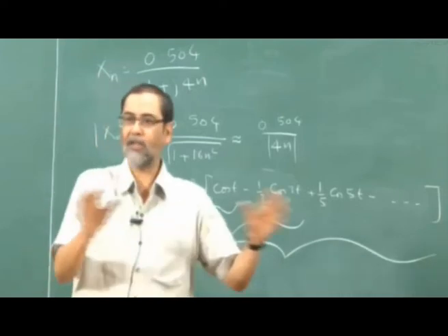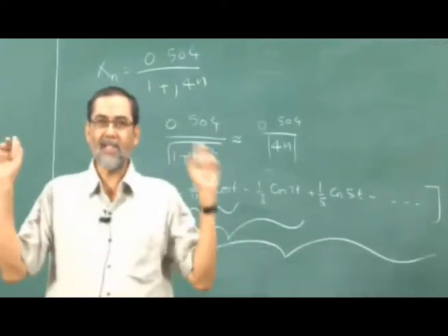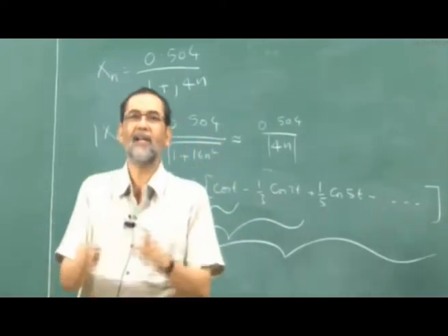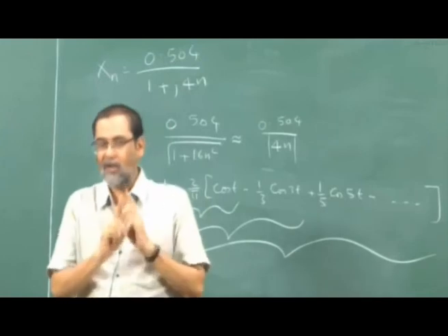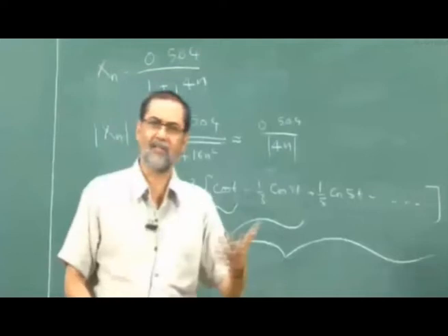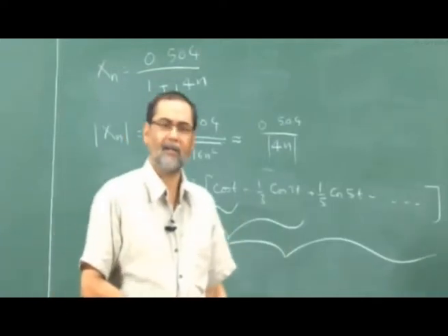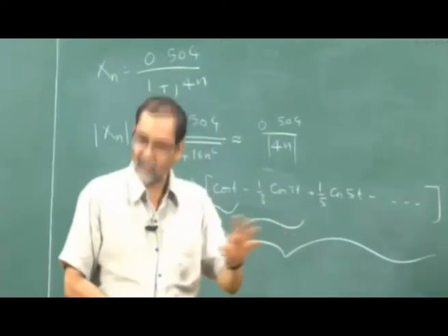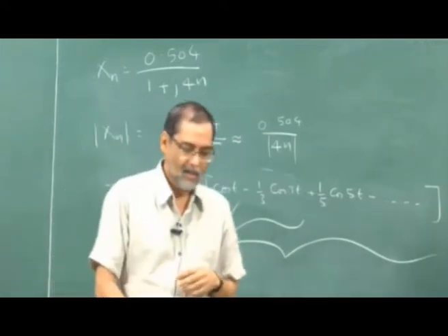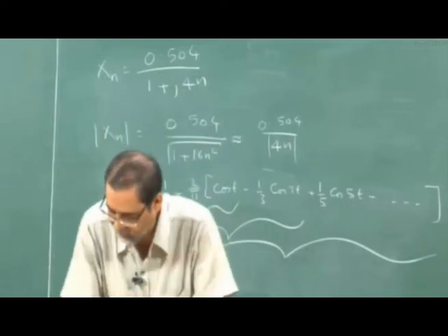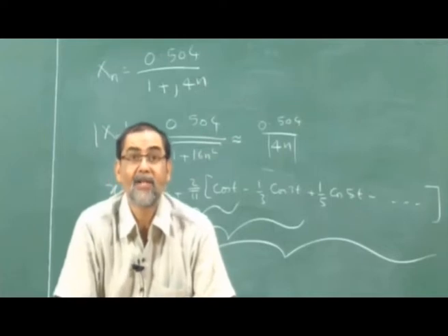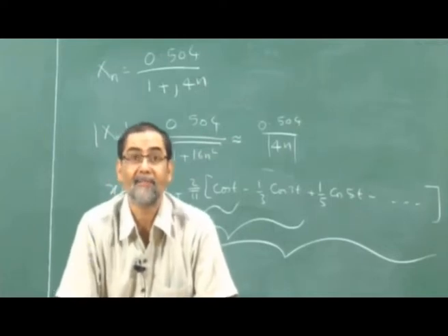Convergence in the mean means both are equal everywhere. So this equivalence the Fourier series talks about for some discontinuous signal is mean square convergence and not the convergence in the mean. So all these ideas took lots of time, 70-80 years after Fourier died. So now we understand that the two might be equal in some sense. Then the question is, can I write Fourier series for any periodic signal?